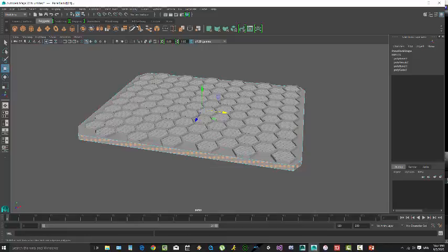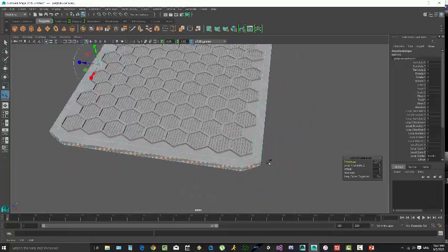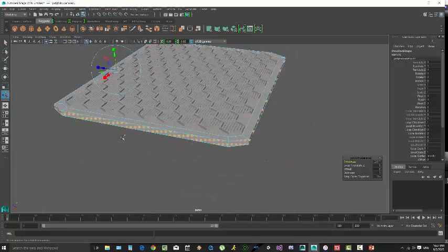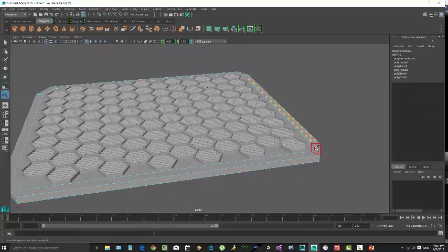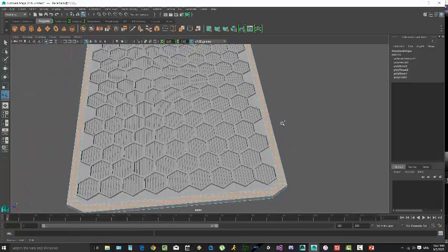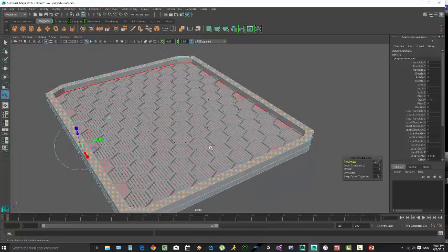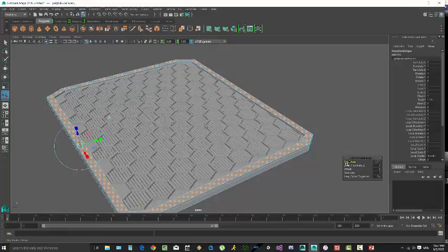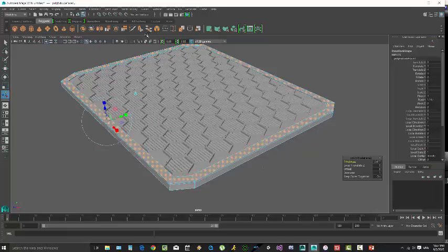We're going to add an extrude for the sole purpose really of adding a ridge for a little bit of visual detail. So now we'll select this face, double click this face to select all the way around. Do another extrude and reduce that thickness down. Okay. Now do another extrude.